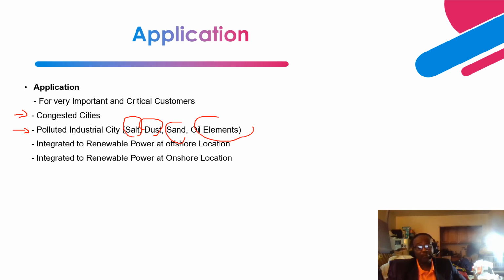Spacing is a premium on offshore substation platforms, because larger spacing means larger costs, and the goal is to fit into a smaller spacing to reduce the cost. So the smaller footprint of the gas insulated switchgear becomes the best option for you to select.